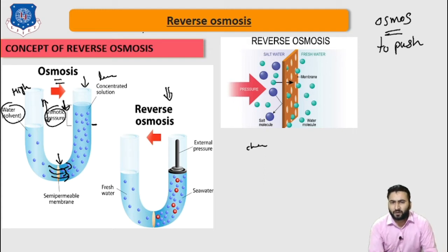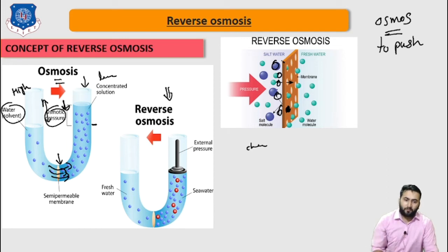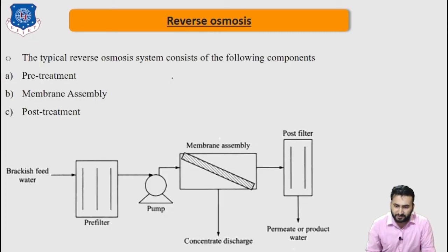As we force water out, the salt concentration increases, requiring even greater pressure to get more pure water, because the salt at the surface of the membrane accumulates and blocks the pores. So we require a large amount of pressure to get the pure water, right? So in reverse osmosis, we require higher pressure compared to all other membrane separation processes.